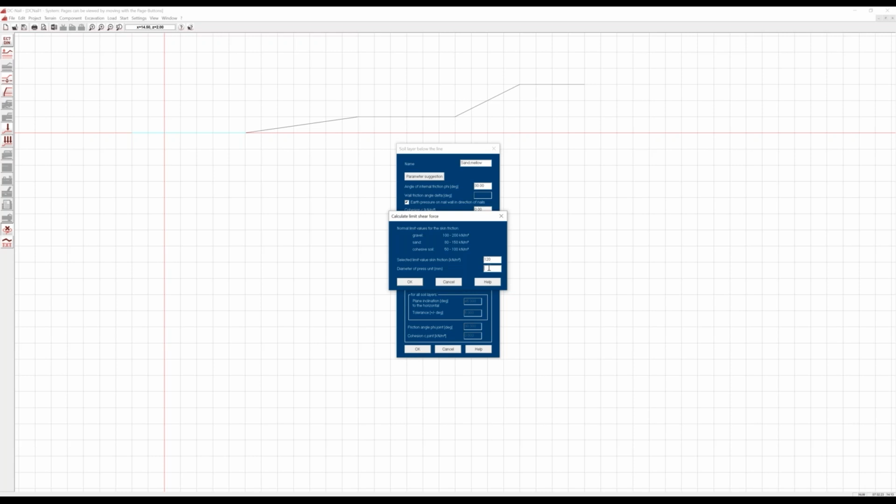And the press unit, the fixed length of the nails, has a diameter, for example, of 60 millimeters. So this skin friction multiplied by the circumference of the press unit gives this limit shear force, so we can transfer 22 kilonewtons per meter length of any nail from the nail to the ground.